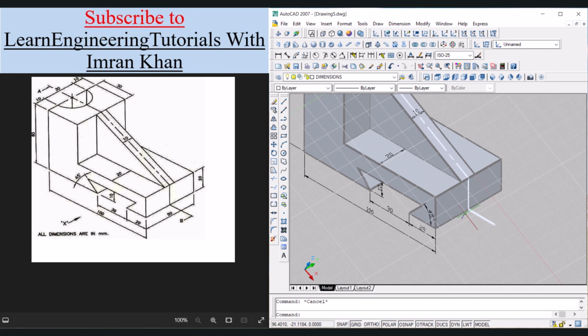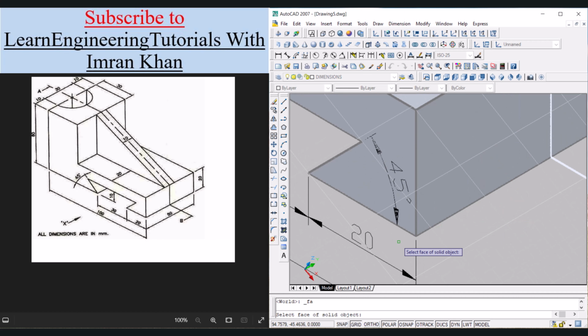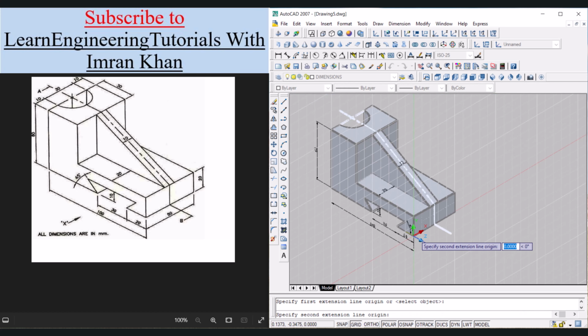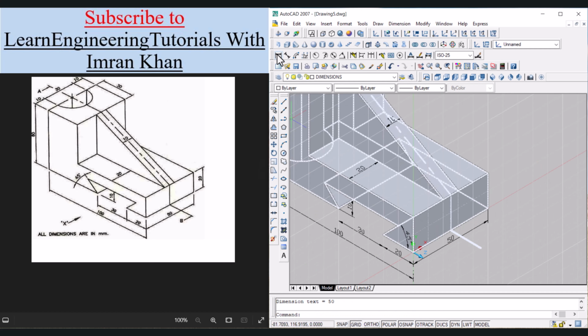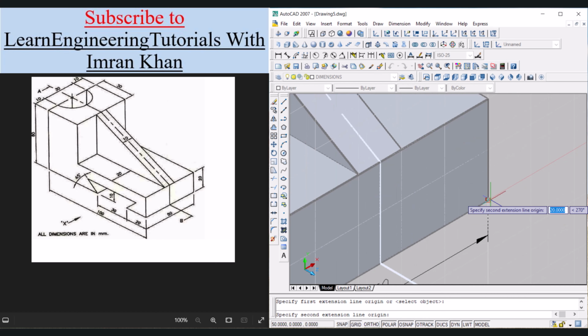Now we have to change the face again. Click on face UCS, click on this face, click on accept. This time click on linear, click on this corner, select the opposite corner, move the cursor in the downward direction and we have to click over here. Click on linear again, select this corner, make sure to zoom in this time, click and click.